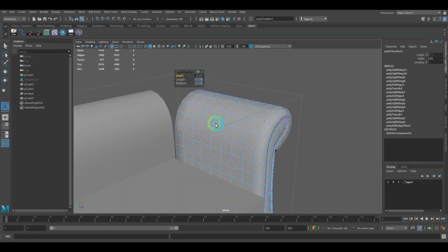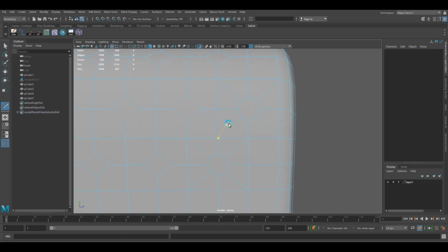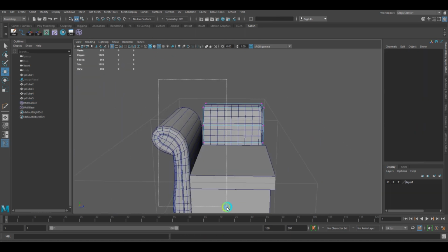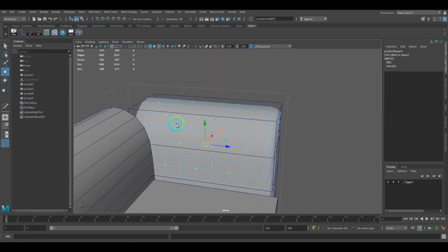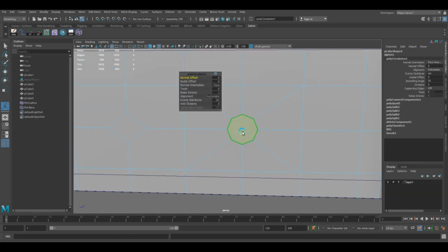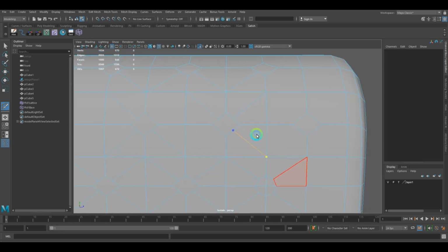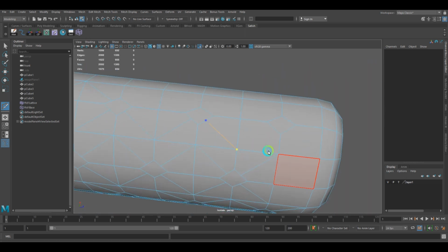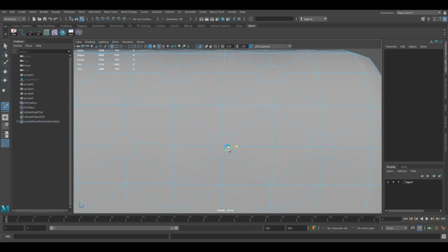Now I am making the Chesterfield in the model and trying to rearrange the edge loops with the cut tool to make it look more smooth. Using lattice to make the model proper. Using circularize components to make the selected faces round.